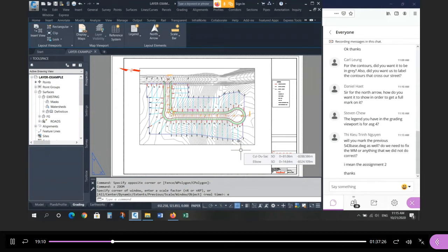Okay, so it takes a little bit of time. So MED next semester is going to be very familiar. A lot of what we're doing here, you're going to do again. Subdivision's different. The topo's different. You need to create an alignment, lay everything in plan, design the profile, model the corridor, get your front lot corners, input the pipe design, and so on. It'll be the same process, just different starting conditions.